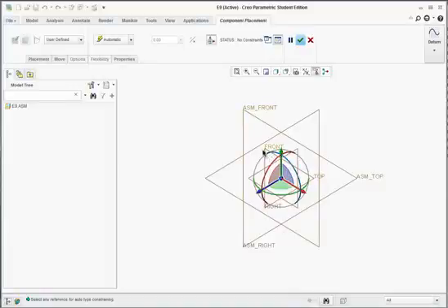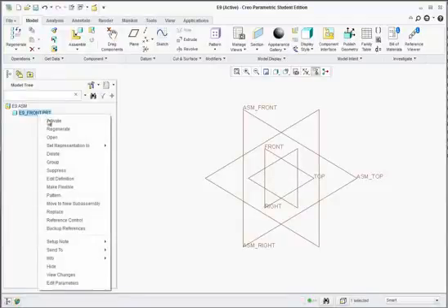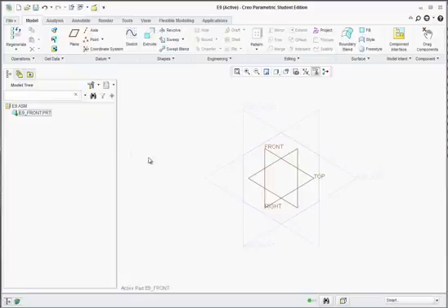And at this point, for automatic, we're going to set it to default so that it locks the centers of our origin, our CSYS, the part in with the assembly. And hit the green check mark to apply. Now you'll see E9 assembly and the E9 front part. Right click on the E9 front part and find Activate. Now we can select the front plane and start our sketch.